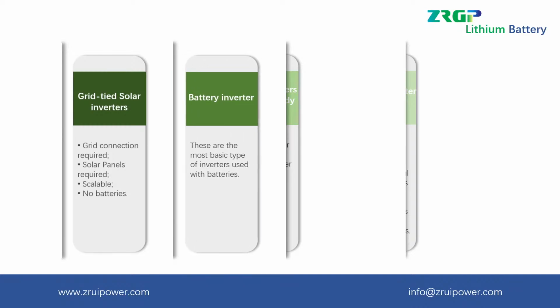Now let's talk about the second one, the battery inverter. The battery inverter is the most basic type of inverter used with batteries. Battery inverters convert DC low-voltage battery power to AC power. These are available in a huge range of sizes, from simple 150-watt plug-in style inverters used in vehicles to powerful 10,000-watt inverters used for off-grid power systems. These inverters are typically coupled with MPPT solar charge controllers connected to one or more solar panels.